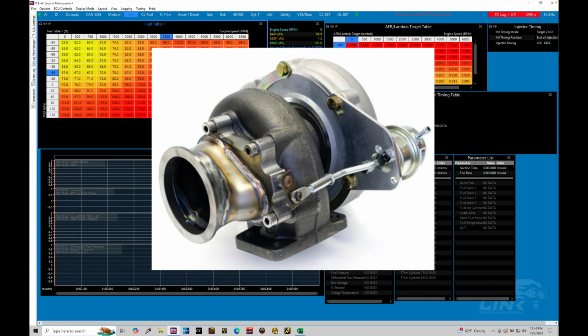So looking here at our first example, this is going to be a traditional internal style wastegate. We're going to find that there are a couple components with the internal wastegate. We're going to find we have an actuator, which is composed of our little top hat and the nipple that gets a pressure reference. Then we have a connecting rod that's going to go between the actuator, and we can see it's going to be connected to a flapper valve. That's going to be found on our turbine housing.